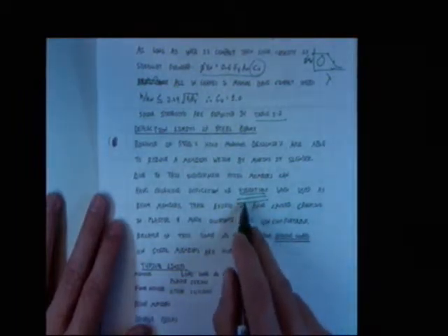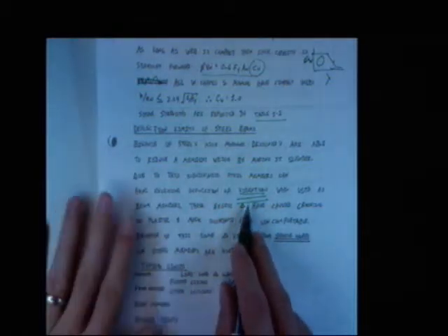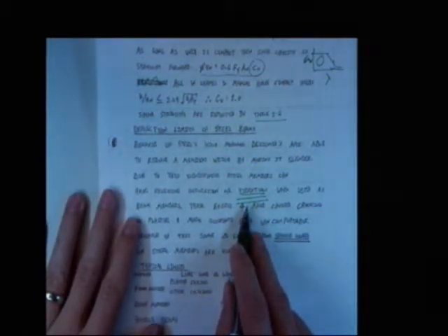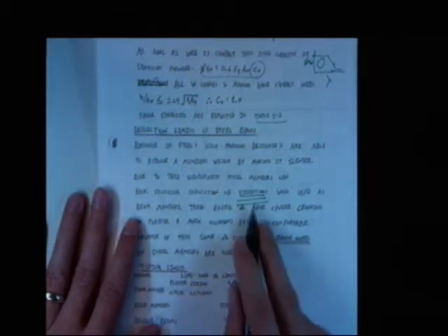And actually, again, if we were to do things exactly, we would do dynamic analysis on structures. We would find out what the natural frequency of the structure is, and compare that natural frequency to the typical natural frequency of loading. Okay? There are some good papers out there on how to do that. It's not that hard to find the natural frequency of a human walking, or of a cart being pushed down a hallway. They actually have numbers for what the natural frequency is in a gym, like riding a bike, and exercise rooms and things like that.